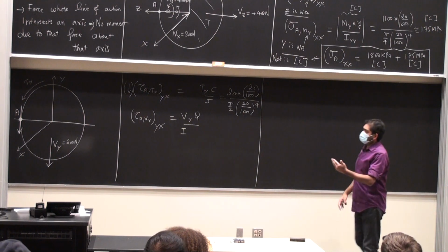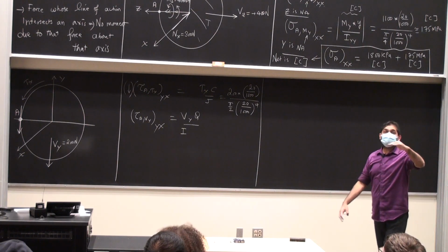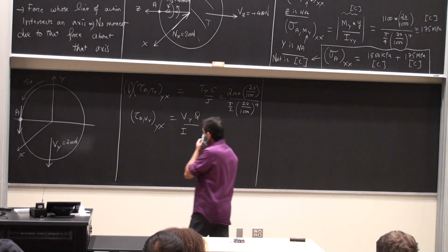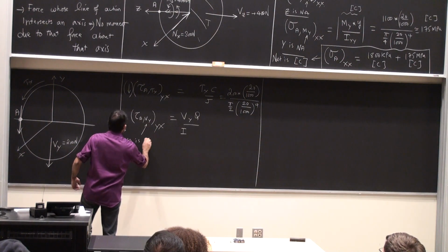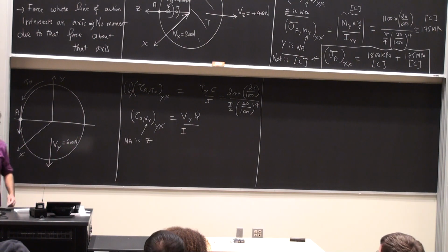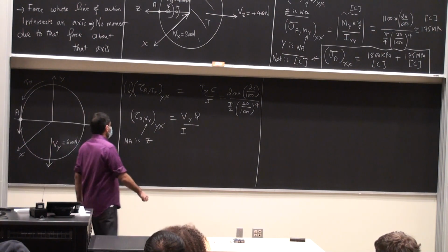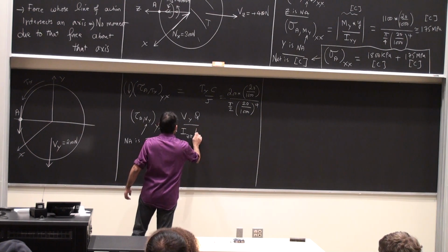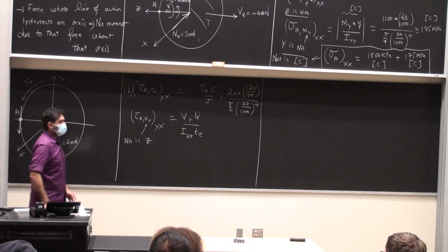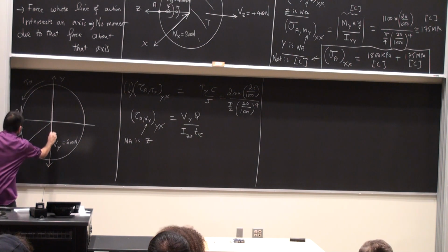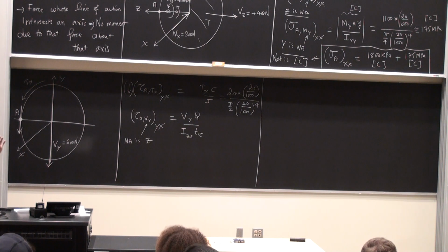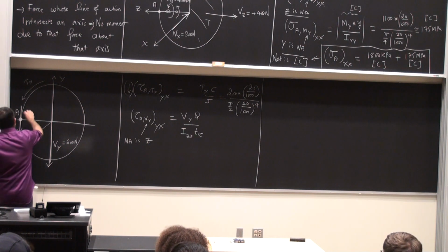Now, if I have a shear force Vy, the neutral axis is the axis on the cross section which is perpendicular to the shear force. So for me here, the neutral axis is the z axis. So this is going to be Izz times t, with suffix tau. We have looked at the calculation of Q and so on, so if I draw the figure out here, I can look at all the area on the top of A or the bottom of A. I can look at the area on the top here.